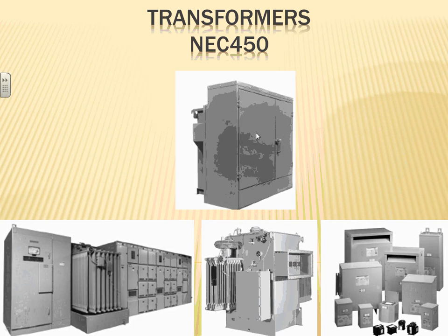So this transformer, the one in that compartment here, tamper proof transformers, that's what we see outside feeding our building. You have probably seen and sized tons of them sitting outside to feed your building. That's usually a utility transformer, though it could also be ours. The ones that we deal with all the time are these in the bottom right here. These are your 480/208/120 transformers that step down the voltage from 480 level into 208/120 to power your receptacles at that voltage, or lights if you so decided.